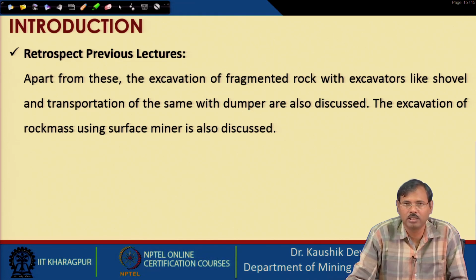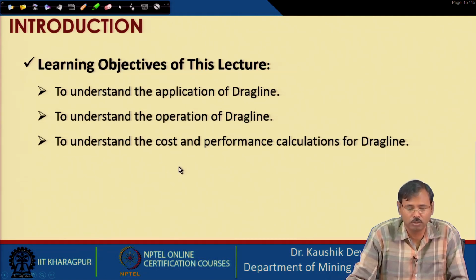It can operate with very high specification, and as the bucket is suspended, its digging depth is significantly high, and the power requirements are also lesser than the stripping shovel. So, these are the facilities of the dragline we found in our previous class. Let us look into the objectives of these 3 lectures on the dragline: to understand the application of the dragline, to understand the operation of the dragline, and to understand the cost and performance calculations of the dragline.